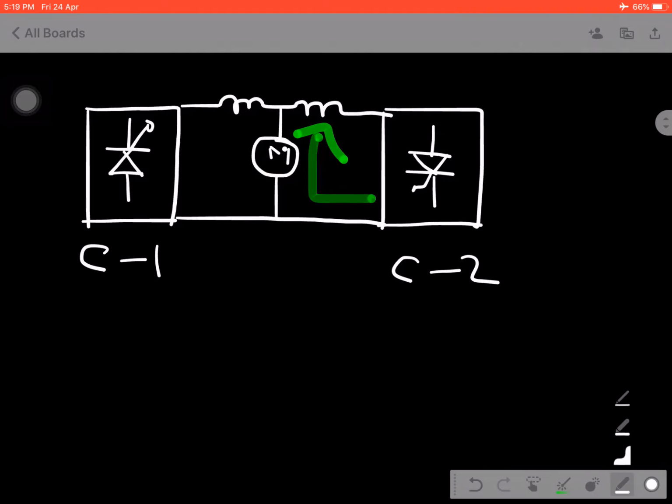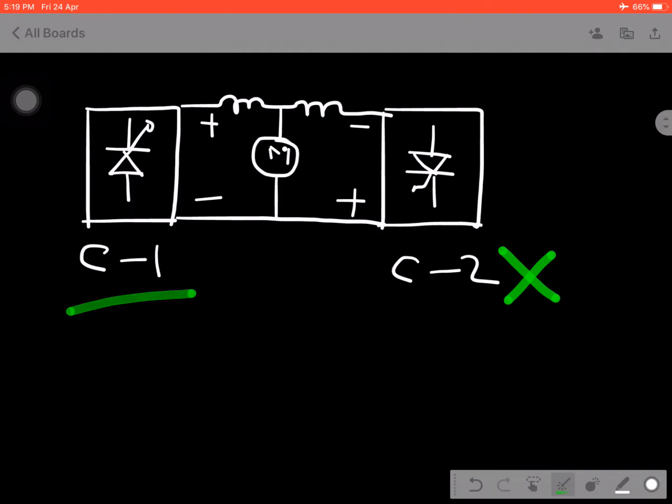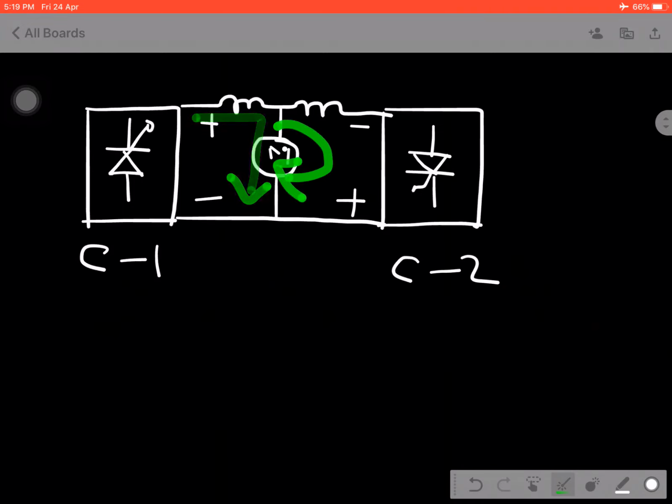As they are back-to-back connected, the voltage polarity across the load reverses, which is why the direction of the current is always opposite. When the first converter works and the second is off, the current flows through the load and the machine moves, suppose, clockwise.